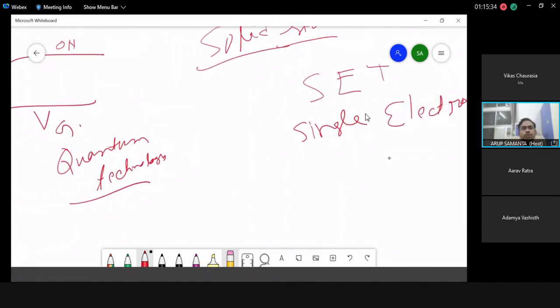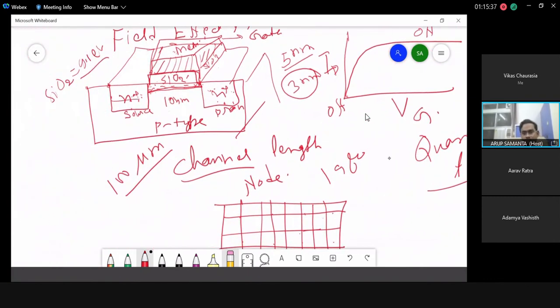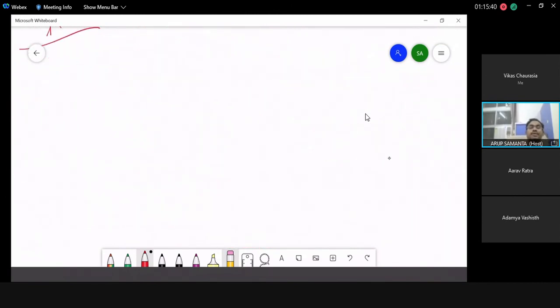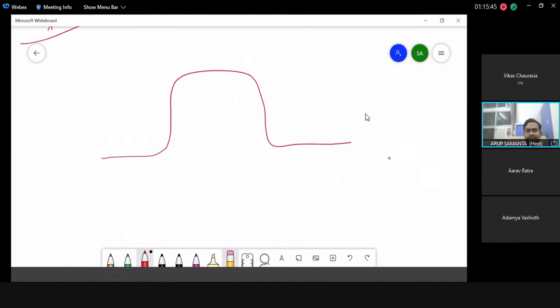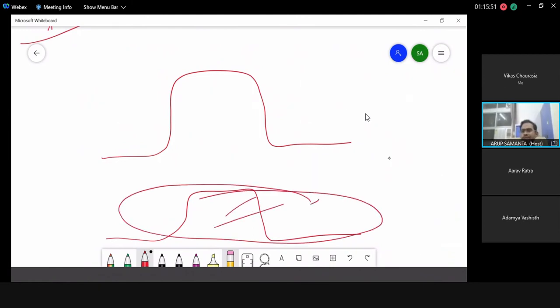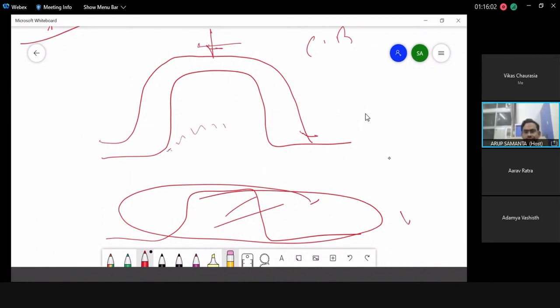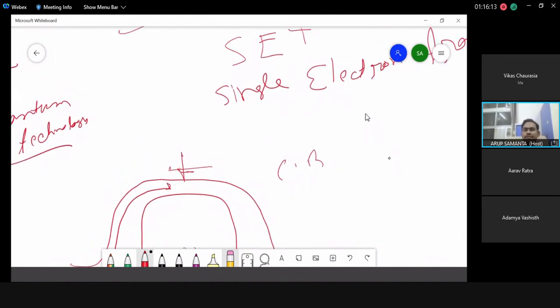If I draw the MOSFET along this, the energy characteristics, the potential diagram in the conduction band, this is the diagram, and the valence band is the same thing. I don't want to focus on the electron transport, so you don't need to think about the valence band. This is the conduction band, this is the transport, the flowing process. Then by applying the top metal gate, you can reduce this barrier. Earlier electrons had to cross this barrier, so the current was low, and after that you get a higher current. So I'm drawing this tentatively.